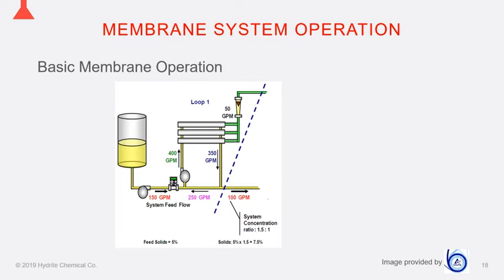So what we put in is a recirculation pump to increase that flow rate into those housings. So I'll have 133 gallons a minute because that pump provides me with 400 gallons a minute. That provides that scrubbing action, cross flow over the membrane surface. And I kind of say that's a little bit like whitewater rapids. It's kind of got that scrubbing action. It's going to move those soils across the surface of the membrane.